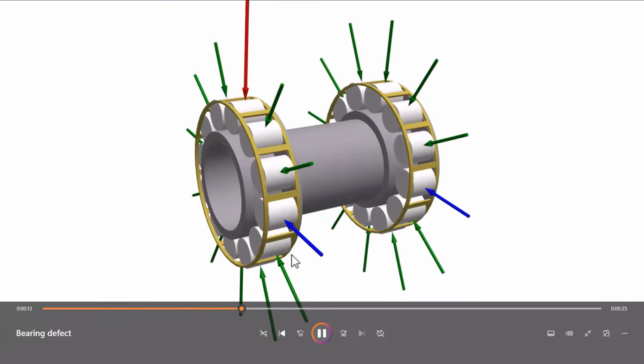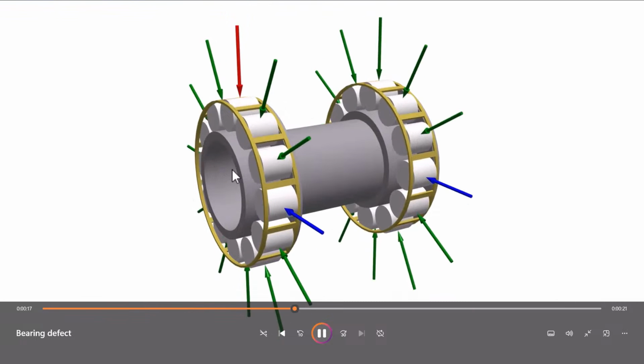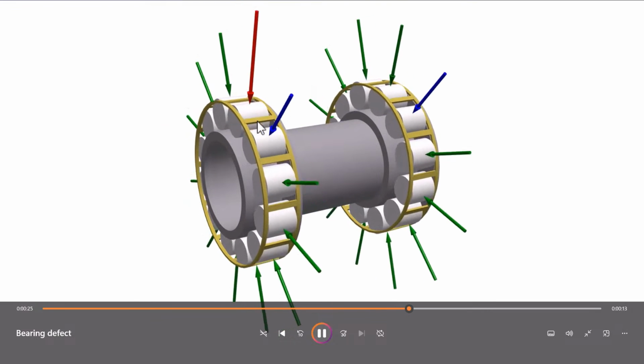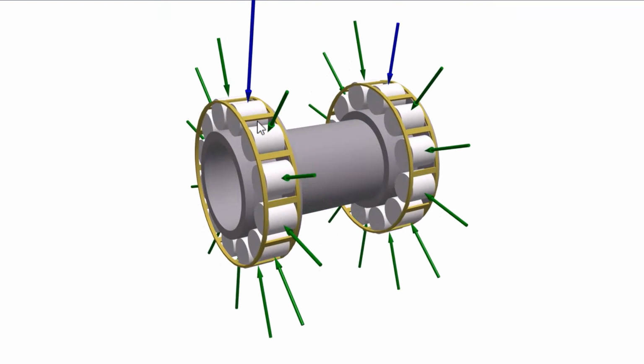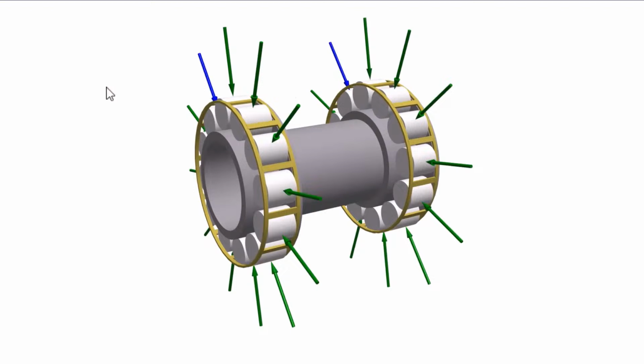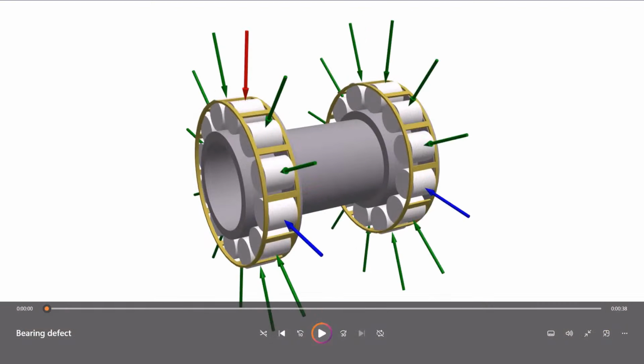If we watch now, it will be coming again. Here we are almost there. Right before and after this position we see the minimum and maximum, and again we observe the minimum force applied to the first roller. By looking at this animation, we see the roller forces, and such bearing simulations, I would say, are invaluable, allowing us to predict and plan for the forces within our bearings, and to understand how clearance, defects, and system dynamics contribute to the overall bearing load profile.